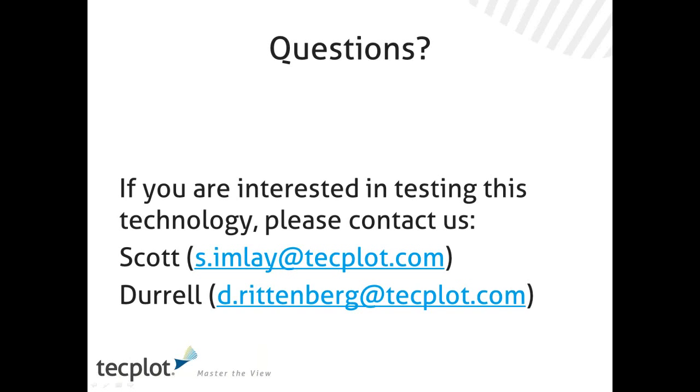But I think core blanking capabilities allow us to do one of the things they really want to do: I've got some particles that are real, so to speak, and some are virtual, and I'd like to turn the virtual ones off. That's pretty easy to do. You can either do that with blanking, or if they remain virtual particles the entire time, you can just put them in a separate zone and then turn that zone off.